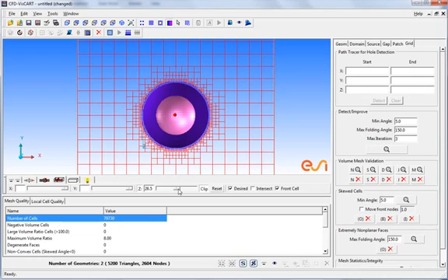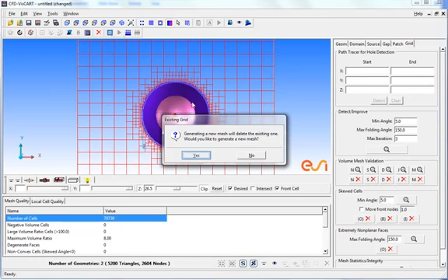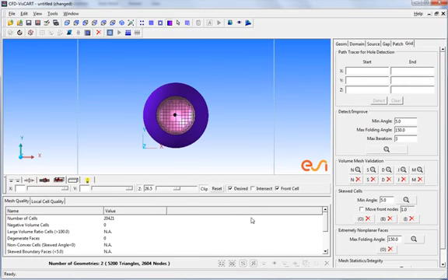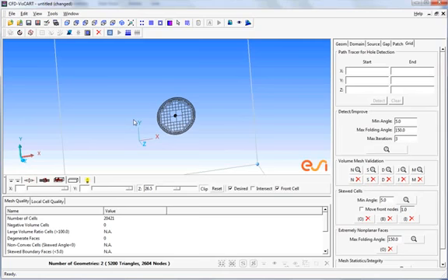Let us regenerate the mesh. When we do so, the mesher will recognize the new position of the domain marker and generate the mesh only inside the inner sphere. As we see here, the mesh has been generated only inside the inner sphere. As before, the quality of the mesh should be detected and improved before it is saved.